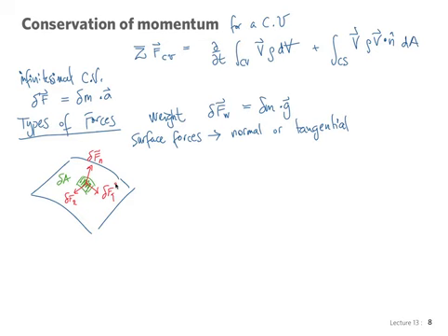So we'll use the concept of stress in general in fluids. For normal stress we use the symbol sigma. Let's use the little n to indicate normal, and it's going to be the limit when this small area tends to zero of the differential of force in the normal direction divided by the differential of area. Force divided by area is stress.